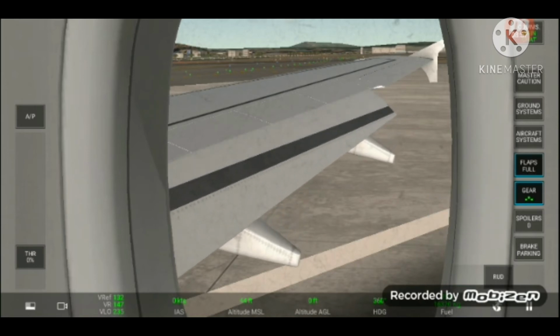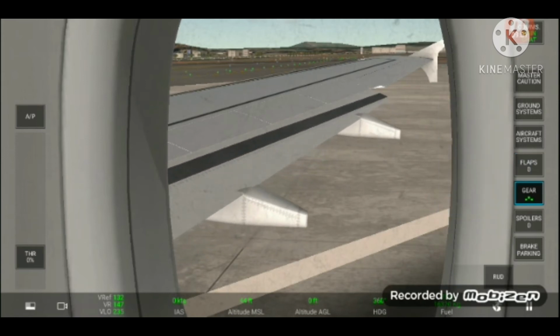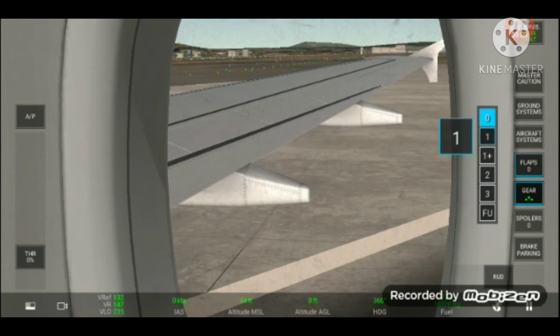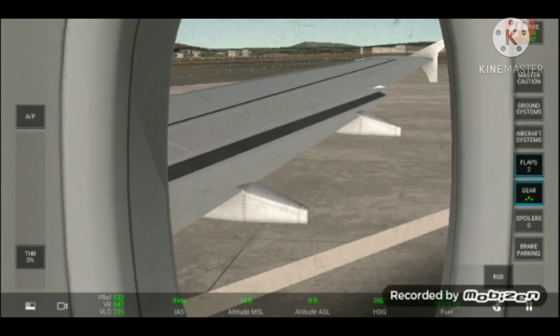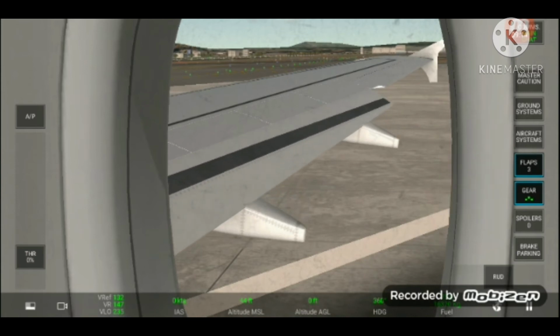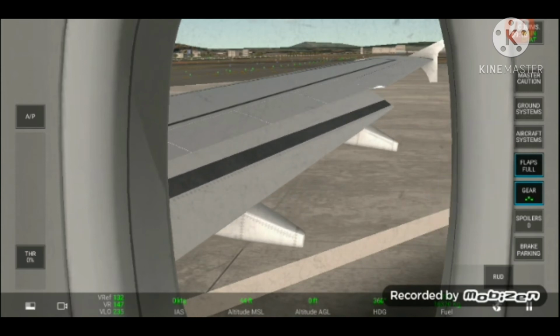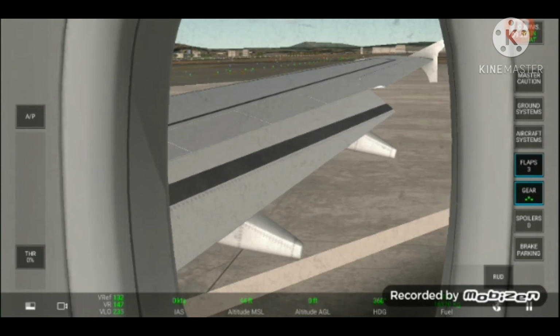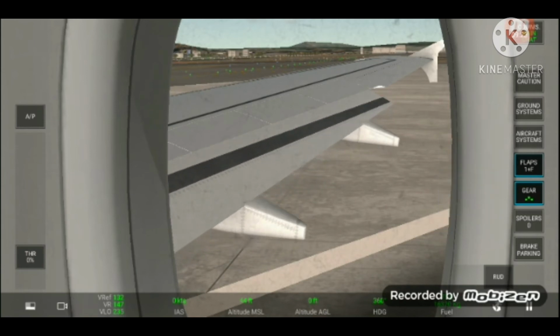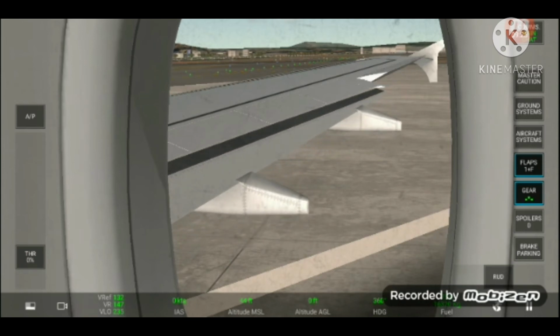Now back to flaps. They are used during low speed, high angle of attack flight including takeoff and descent for landing. Some flights have inboard flaperons, also called inboard ailerons. This device functions primarily as ailerons, but on some aircraft will drop when the flaps are deployed, thus acting as both a flap and a roll control inboard aileron.